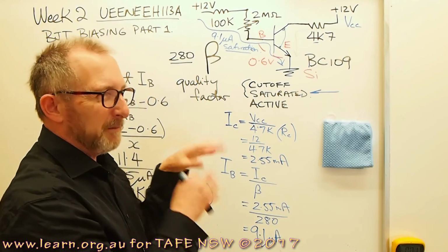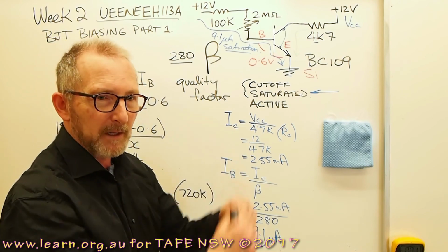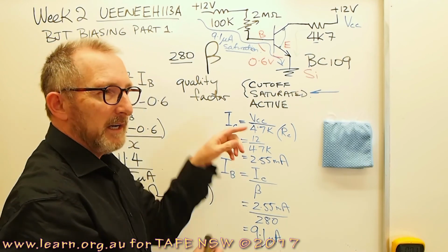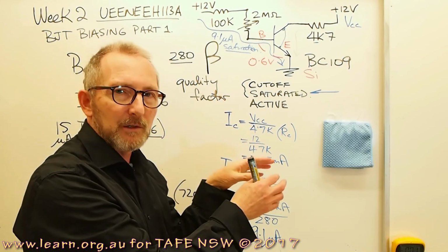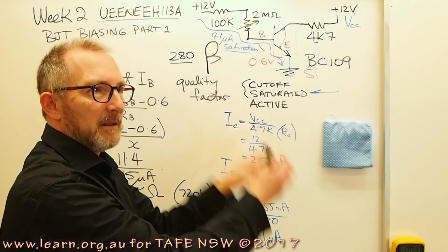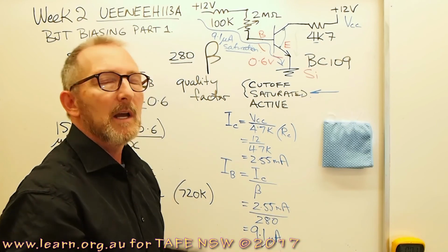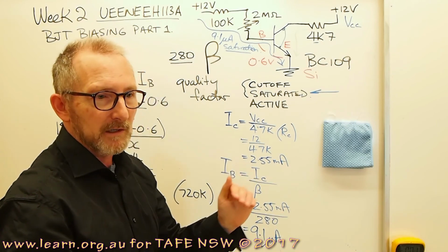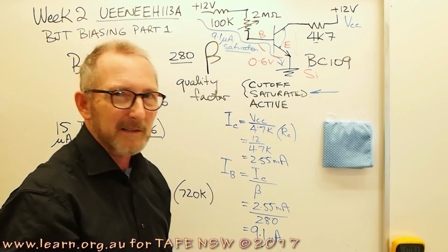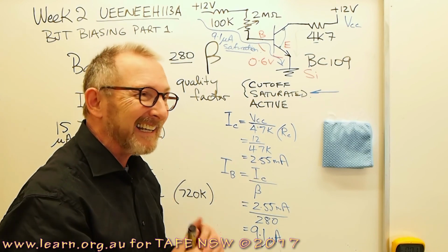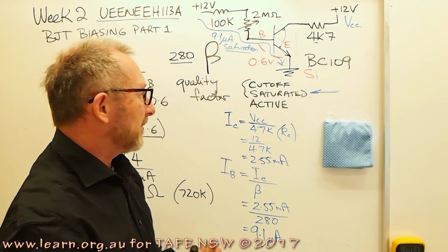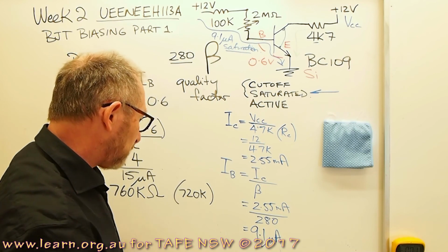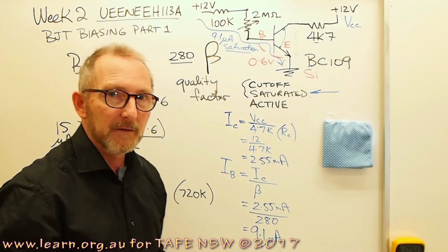And then maybe don't be so fierce with dropping the value of resistances, because it's only a few microamps, but in a larger circuit, a few microamps here, a couple of milliamps there, and sooner or later you've increased your total current demand by maybe 27 milliamps in a battery circuit, and you're going to flatten the battery that much quicker.